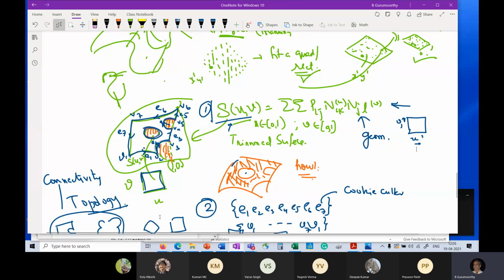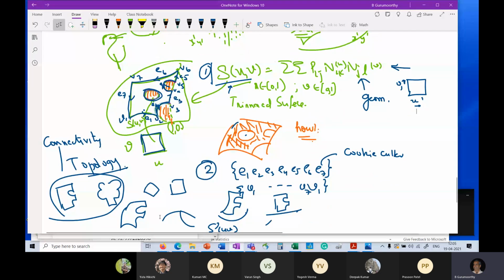And then we highlighted that there are two parts to the representation now. One is what we call geometry, which is the underlying surface that we start with, defined the way we have studied so far. And then we go in and identify the portions of that four-sided patch that we are interested in for this particular surface patch. We call it a trimmed patch, and we represent the boundary of that in the parametric space using the edges that form the boundary.